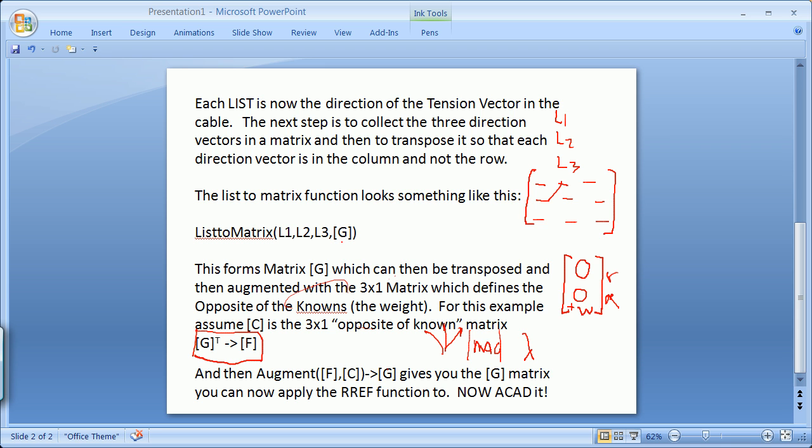And because your list 1, list 2, and list 3 originally were describing a direction, you can go ahead and stick it into AutoCAD by using the at function to get a unit vector, and then using that direction, either scaling it or whatever you're going to do to sketch up your concurrent forces. And in the end, you should be able to add them in 3D tip to tail to check. That's how you do it.